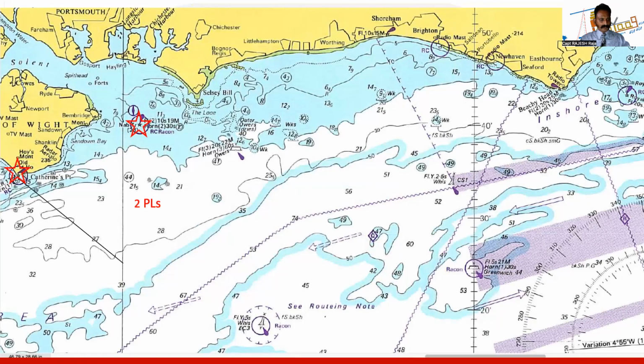So I'm going to draw the bearing. Please remember, bearings are always taken from me to that object, but when you draw it, you'll have to draw on the reverse. Because you are anywhere on these two black lines, and if you sit on that black line, you will always find the bearing that you found out is correct. So please be careful on the bearing part of it. Okay, don't draw in the opposite direction.